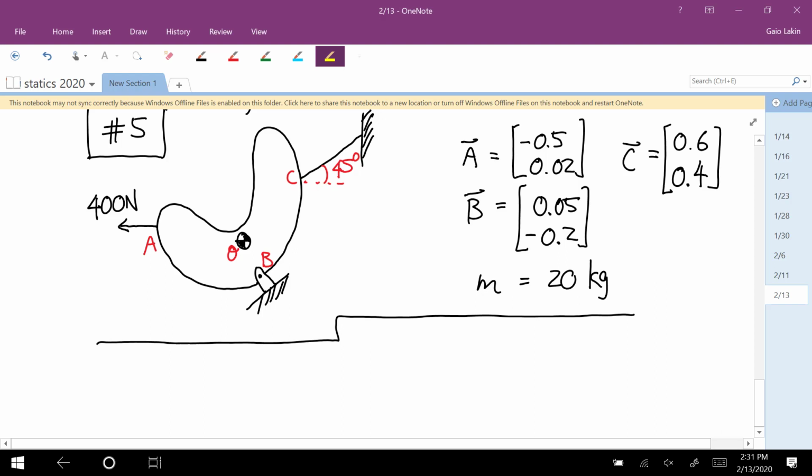So when we do this, we'll represent that as a horizontal component and a vertical component, and then we'll put the vector symbol over it to indicate that that variable has two components. So if it's the contact force with the normal and the friction, then you have the vector sign above it. Yes, because you don't know the direction then.